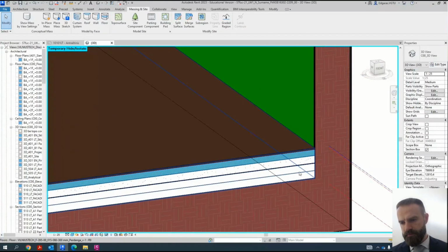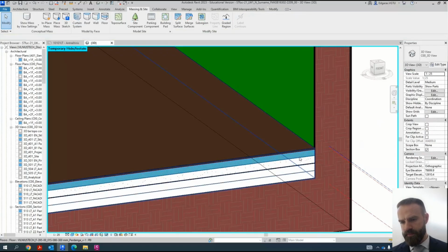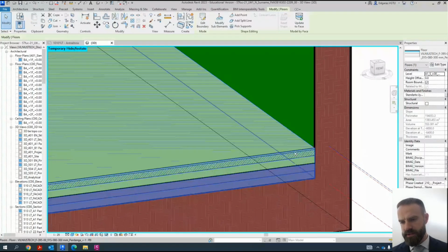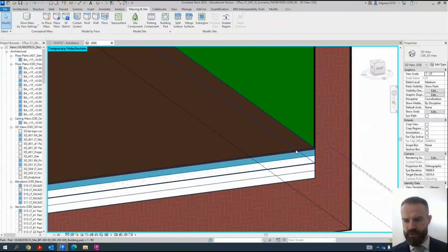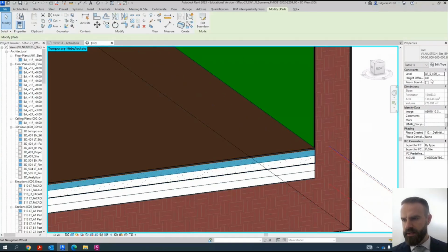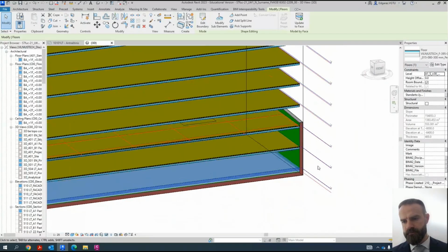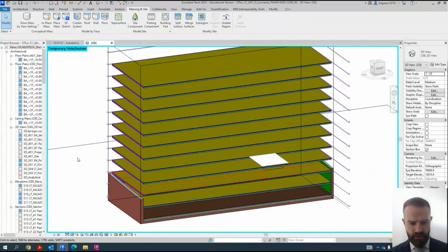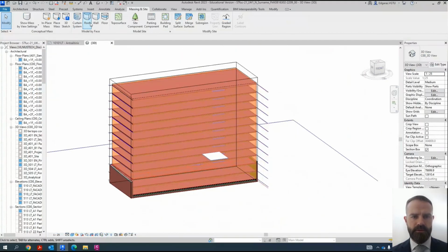My ground floor in this case is on the bottom floor, okay, but in this case I have two objects in the same place, so it means my building pad should go down. So using tab I select building pad and move building pad by -400, and the building pad is below my floor, and now I have nice floor here. So now I create floors, I can restore the hidden objects, and now I can create, let's say, roof.